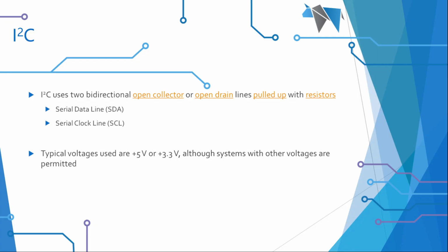Typically voltages of 5 or 3.3 volts, but other voltages are permitted. And be careful, just always check your voltages with these types of devices. I'm using a 5 volt device. A lot of devices are 3.3. Beware of voltages.